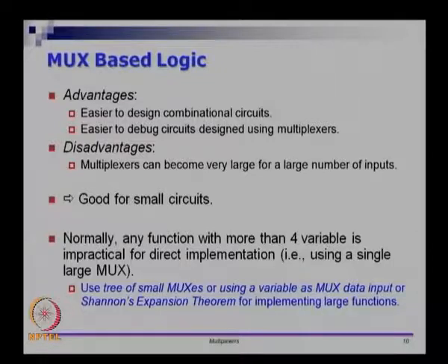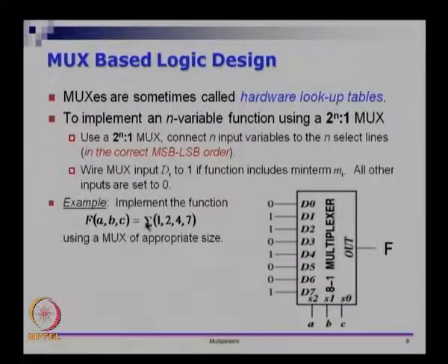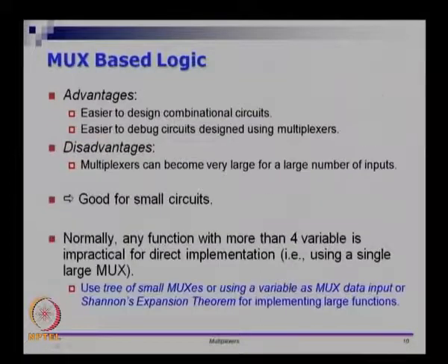However, it comes with a disadvantage. The problem is that muxes can become very large for a large number of inputs. In this case, we didn't do any minimization. There is some structure to the problem here, but we didn't see any structure, we didn't minimize anything, we just stuck the truth table here. So the circuit may get very complicated. You may actually spend more to do even simple functions. So mux based design is okay for very small circuits. It's not good for larger circuits.